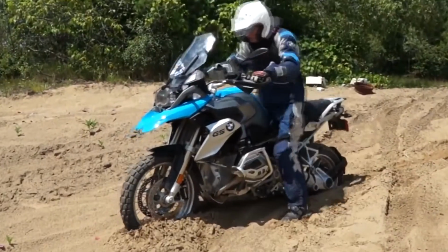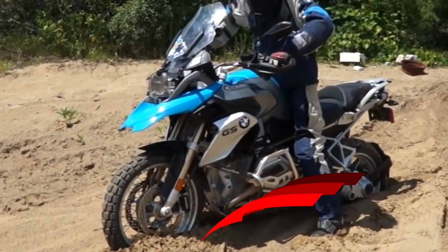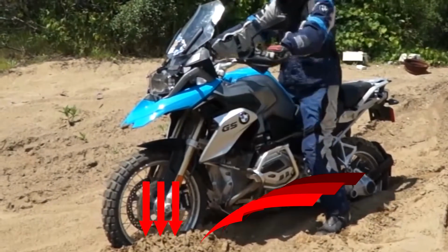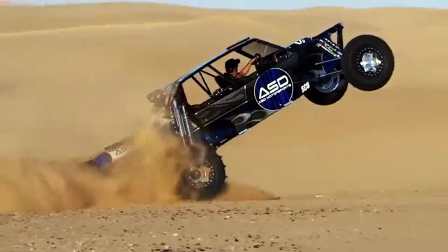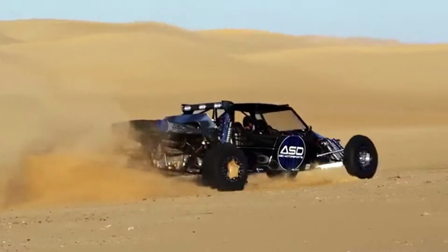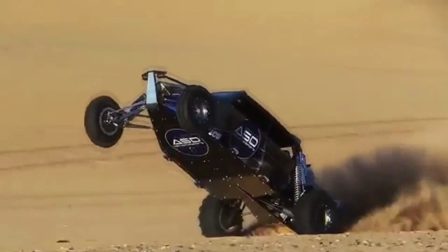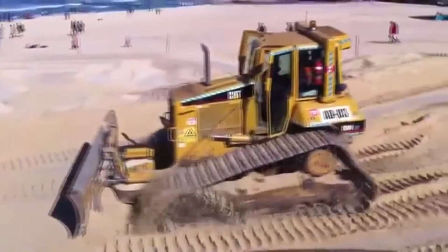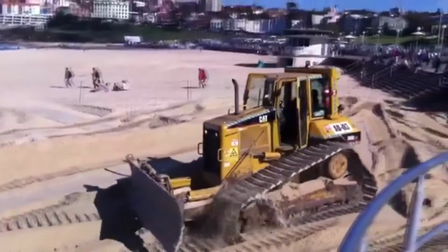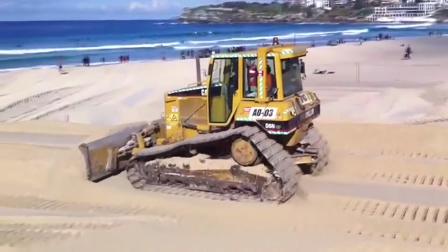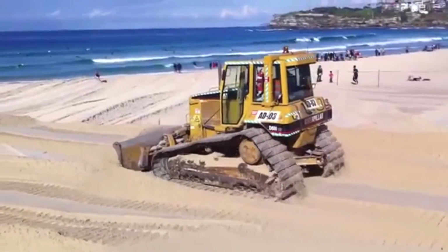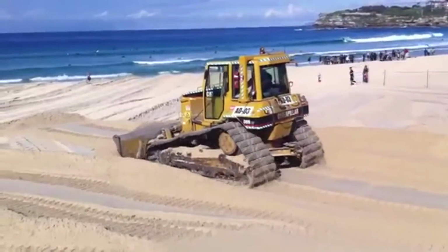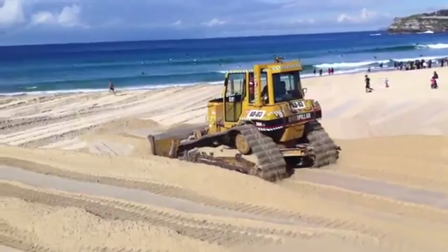This is because a narrow wheel exerts a lot of pressure on the surface, causing it to push itself down into the terrain. Wider wheels have larger surface areas, preventing the wheels from getting stuck. One good example of this are bulldozers, that use crawler tracks rather than wheels. Since they mostly operate on muddy terrains, the large surface area the tracks provide prevents the bulldozer from being stuck.